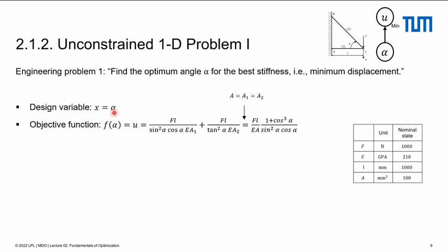So we have one design variable alpha now, and we want to modify it such that it maximizes the stiffness. Everything else will be the same. So Young's modulus, density, everything else will be fixed. We can only play with alpha. And you can imagine if you make alpha very large, you'll make this rod very large, so you'll add a lot of mass. But when you make it too small, you have a very bad angle to support that vertical load, because that'll be supported by moments. So probably the best angle will be somewhere in the middle.